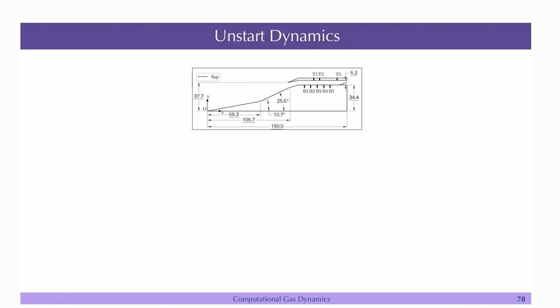Okay, so in order to mimic the pressure rise due to combustion, what we have used is a throttle. The domain is like this, but then we use a throttle like this. Basically there is a blockage here, and because of this blockage the nature of the flow is that it will try to push this on the upstream side, and that may lead to unstart.